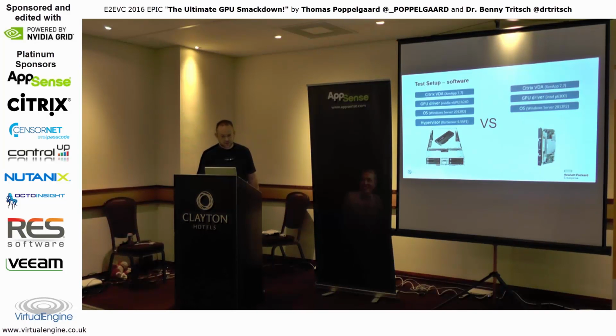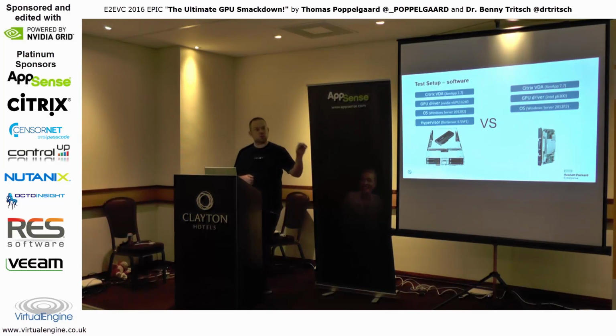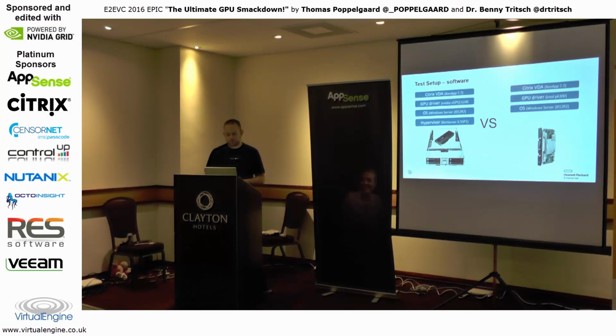Okay, so what did I do here? Again, this is a 7.7 setup. I'm using at that time XenServer 6.5, Service Pack 1, virtualizing it, putting in 2012, and I put in a vGPU driver. Normally I would do pass-through, but this is more for why I'm doing this, because I'm going to create a 1 GB frame buffer. Okay, I want to limit the GPU. And so the same thing that's happening actually in the Intel is also 1 GB. So that's the P6300.